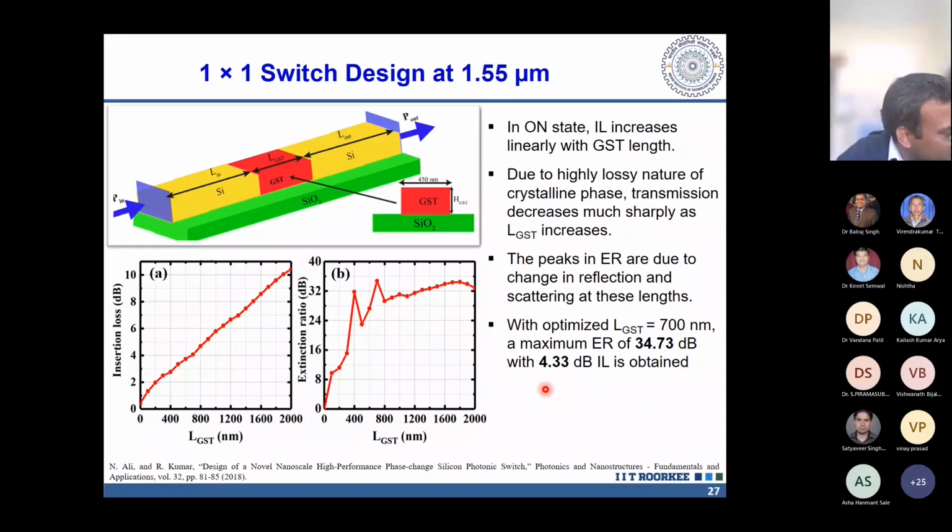If we talk about optical modulation, then what is the range for extinction ratio in fabricating that modulator? So first of all, the extinction ratio comes from when you measure. This doesn't come from the fabrication itself. Now when you do modulation, there you actually want higher speed and high extinction ratio.